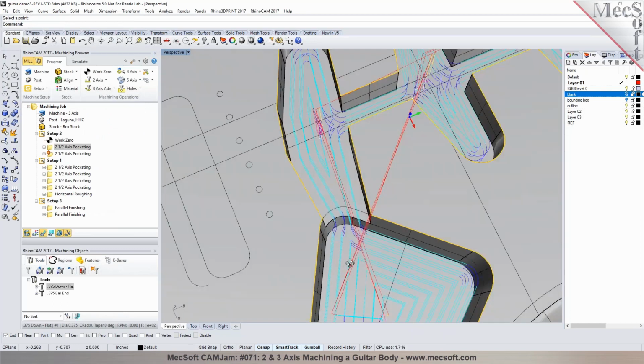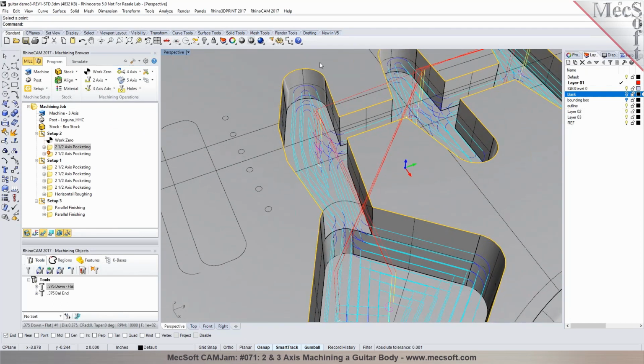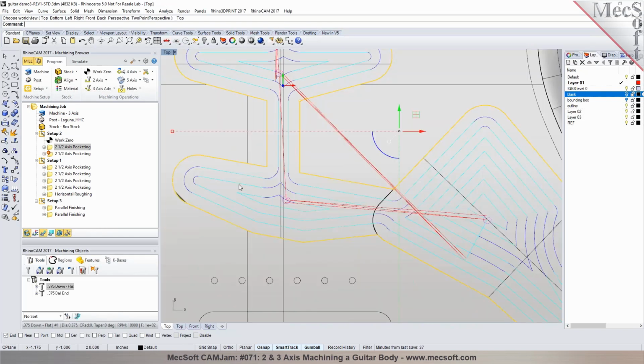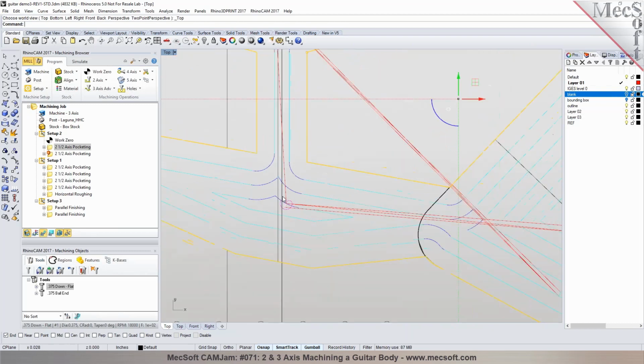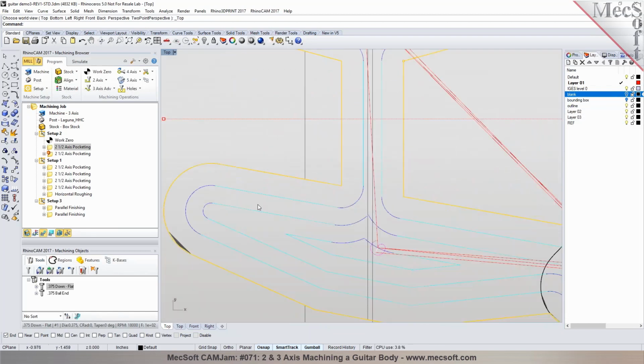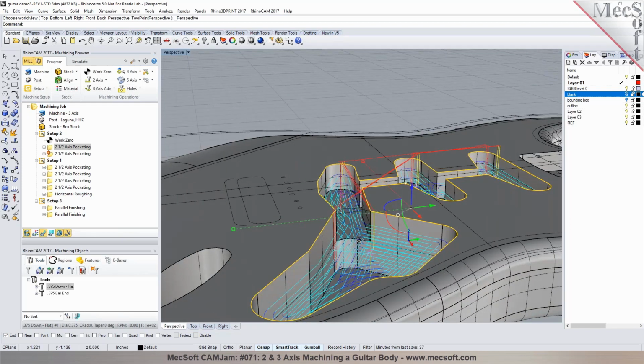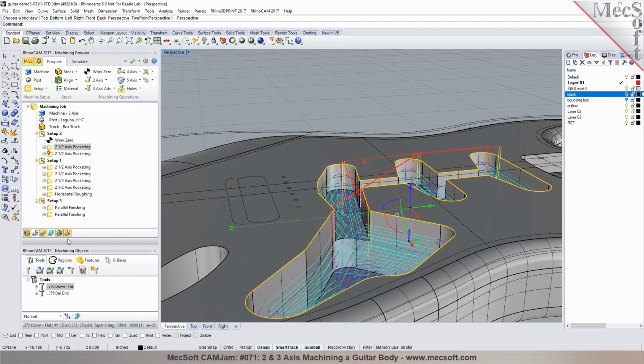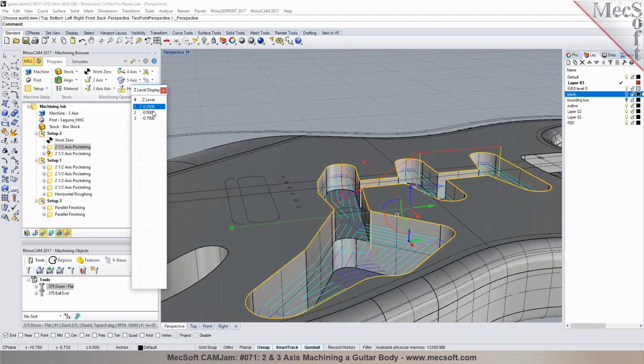So what you see here is an offset cut pattern, let's go to the top view and I'll show you that. You've got an offset cut pattern based on the shape of the geometry that you selected. So this is your offset distance here, okay? And each Z level is your depth. You can look at each level too. So it's got 3 levels at 1/4 inch apiece.